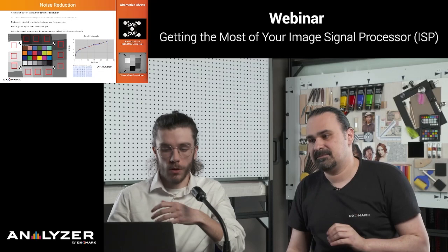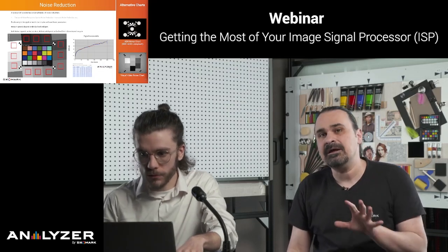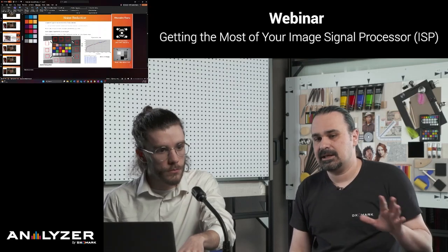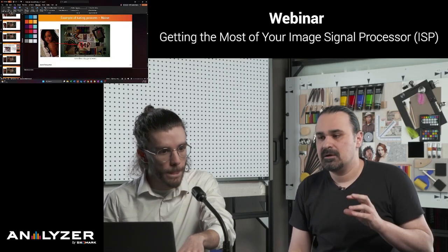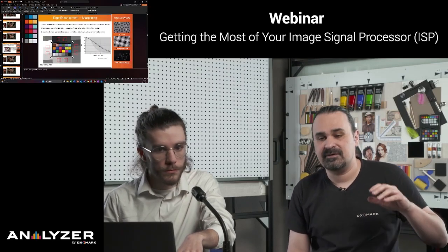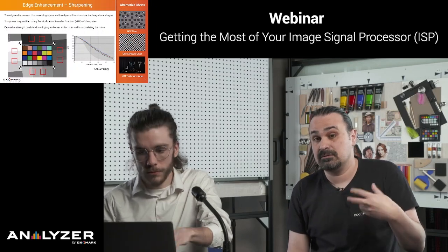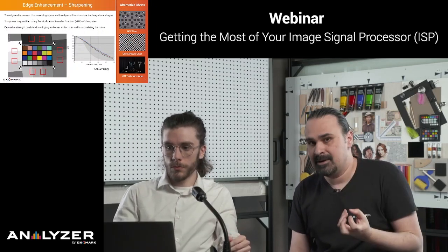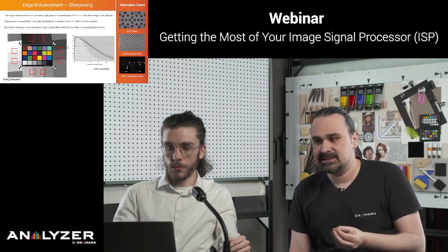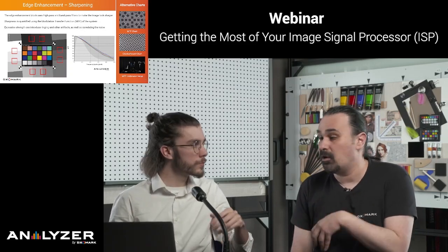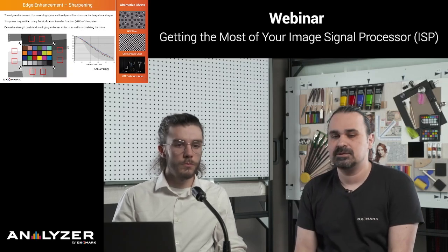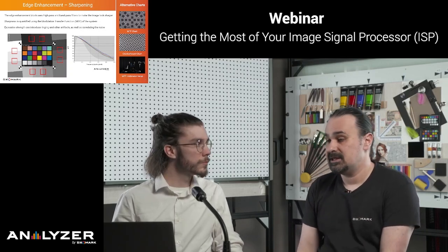Acutance is slightly different because acutance is a scalar metric that you extract from an MTF curve. So it's an integral measurement where you take your MTF curve, you give different weights to it depending on your contrast sensitivity function, and then you integrate all together. So at the end, you get a number. It's typically easier to make decisions based on a number than on a full curve, so it's a good idea to use the acutance.